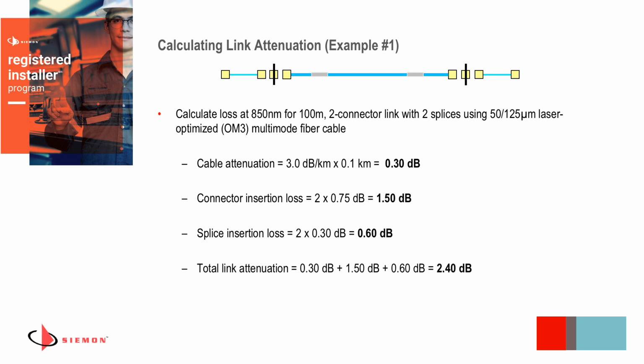So when testing, you're going to want to ensure that your tested installed fiber cabling system is verified to be at less than 2.4 dBs to ensure proper installation. In some cases, as I mentioned, if you have better splices or your connector losses are specified to be lower than that, you may find it to be less than that. But this is a TIA standards-based limit exercise.